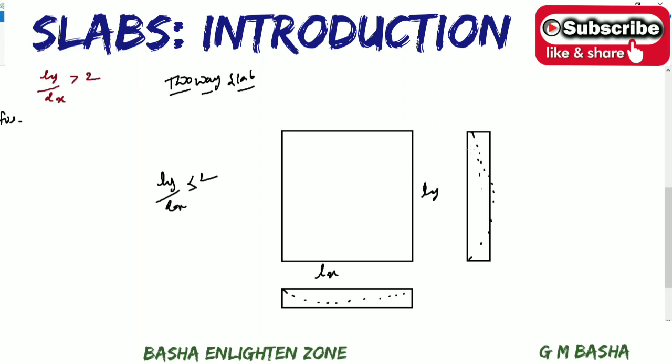Therefore we require main reinforcement in both directions, in the x direction and again in the longer span direction also. These are the bars, straight bars. It bends in both directions, therefore main reinforcement is required in both the directions.